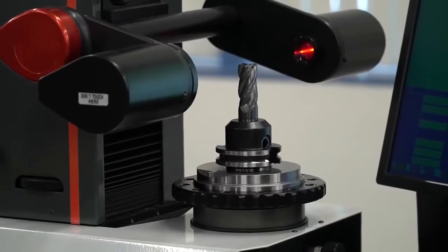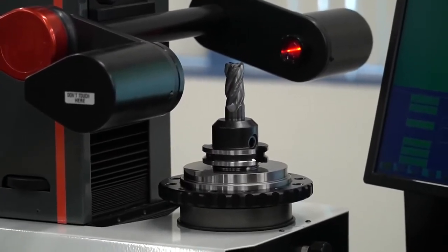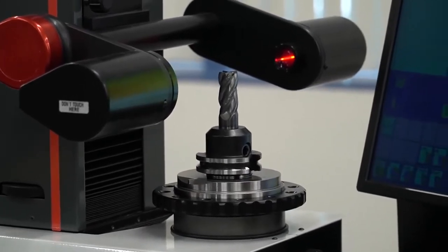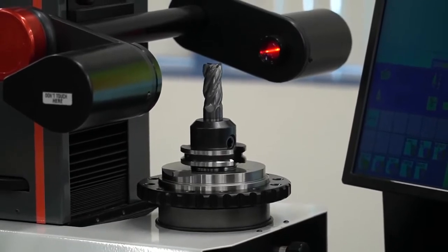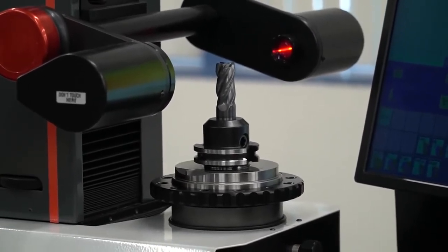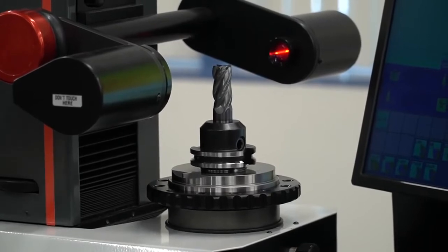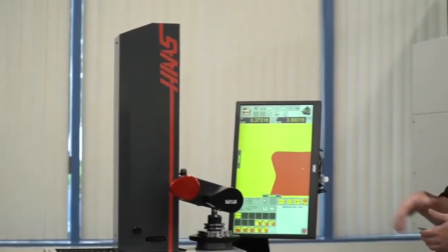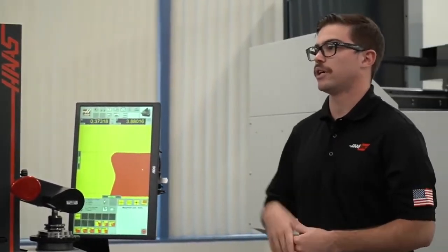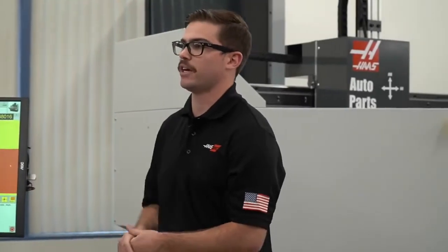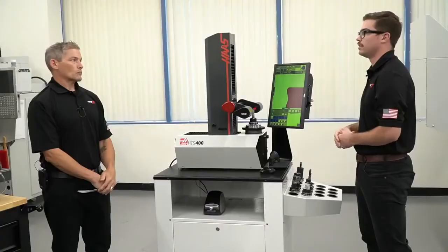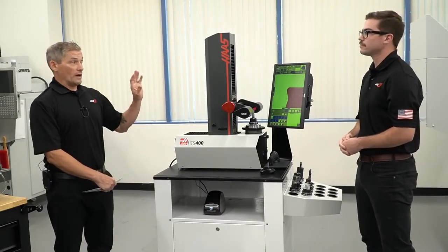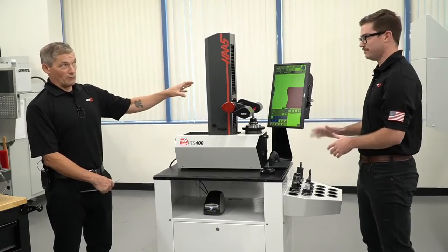So once you've created a folder in there, let's say you checked a tool initially, then once you load a new end mill or put new inserts in that tool, you just come back here and measure it, and it updates that particular tool. You select that file and update that one as the length and diameter change slightly, right? Correct. You can use this if I'm touching off a brand new tool, or for part inspection, where I pull the tool from my machine after a job, put it back on here, and measure the new tool geometry after I've already machined with it.